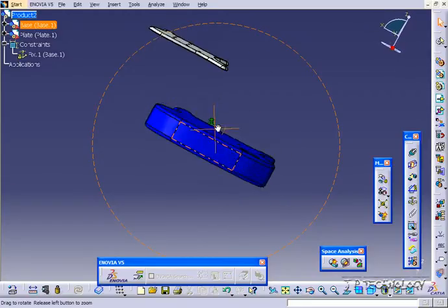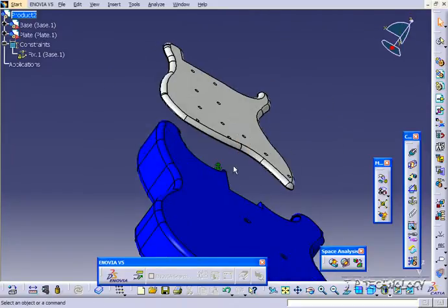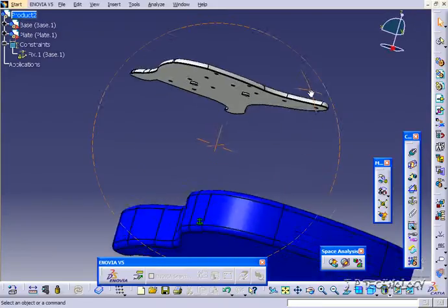So what we need to do is I've created a few pilot extrudes here. So these extruded circles are going to have to go into these cutout circles, and then we're going to have to create a coincident constraint between these two extrudes and circles, and then we have to make a contact constraint between the two faces. So let's start off with the circles.